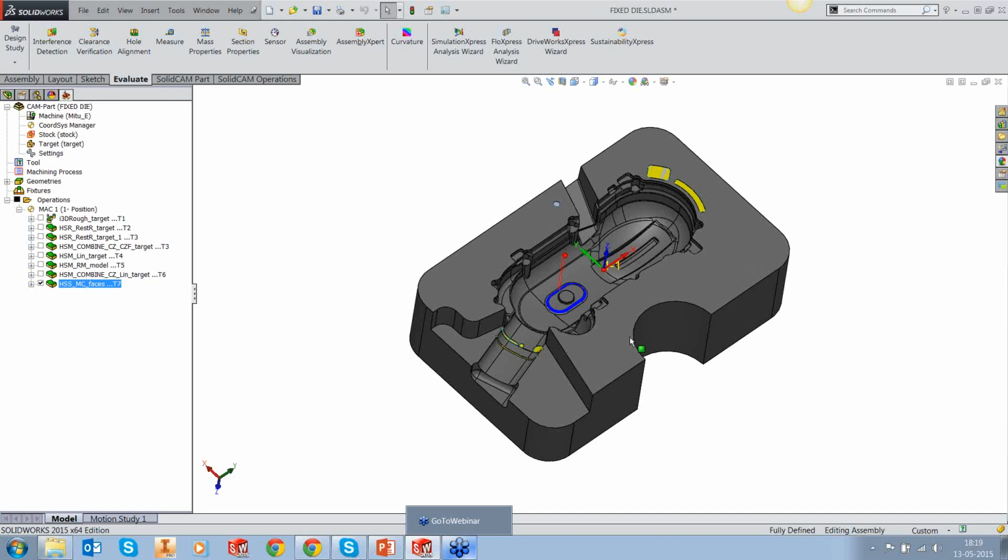For example, in this case, I could do iMachining 2D and 3D only for this particular area, just to open out, because there it will be well within the limit of the tool life. It could scoop out maximum material in the minimum time, and in the remaining areas I could use HSR. So this decision of whether to use or where to use iMachining 3D and HSR is at the discretion of the user.